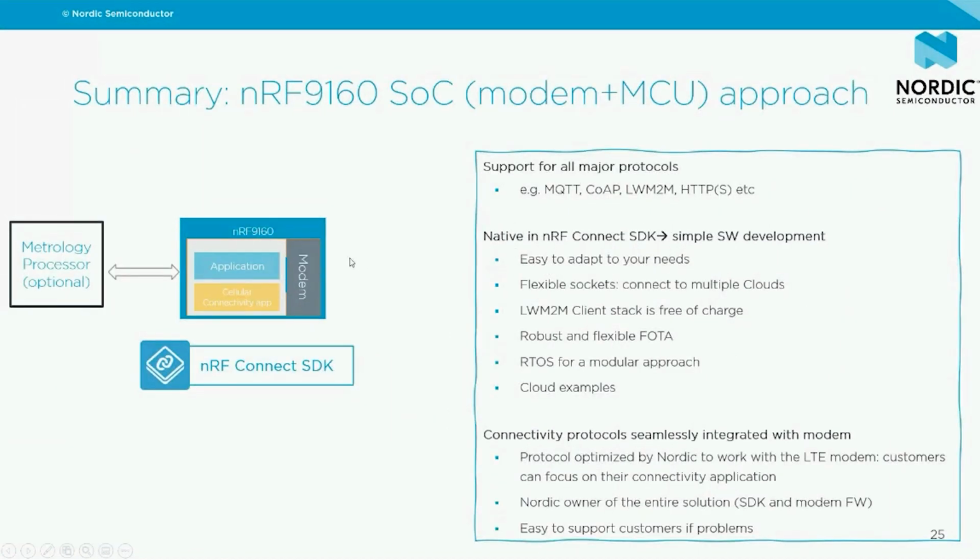So in summary, if you want to use the 9160 and use what we call the system on chip approach and write your complete application here, we basically support all the protocols that you would need to run for a typical utility metering application. We have a fully open SDK used by basically thousands of different customers, so really mature, with really a lot of examples and really a lot of contributions. And then we support both LTE-M and narrowband IoT, so that you can build a solution that can fit any requirement that you have in your end environment.